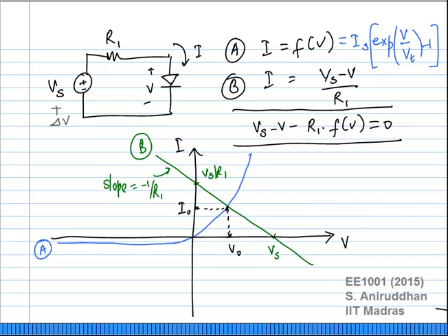Why not? Because the circuit is nonlinear, because there is a nonlinear element inside the network and I can no longer use superposition. That's number one. Is that clear? So you cannot say what happens when you add Vs plus delta V. Suppose Vs was initially 5 volts, and if I apply 10 volts, I cannot say it is 5 plus 5, right? I cannot say it is just double the original voltage, because very clearly the relationship is non-linear.